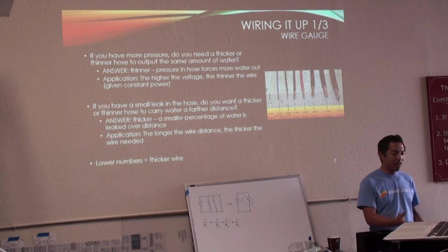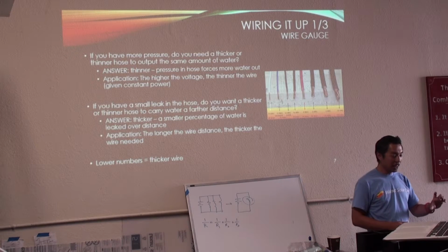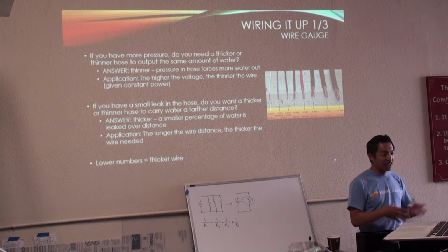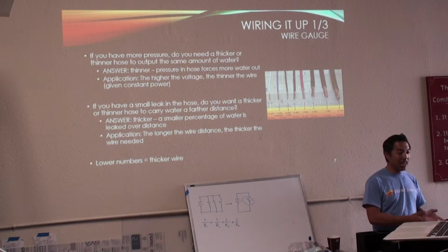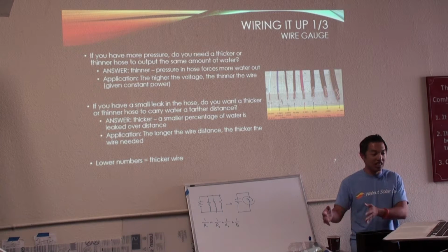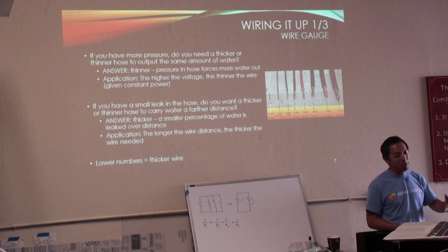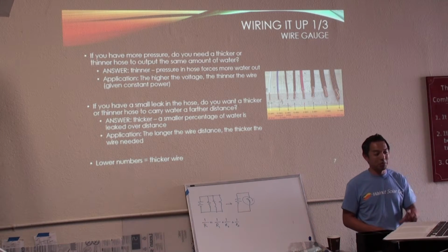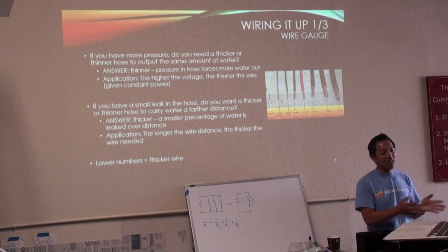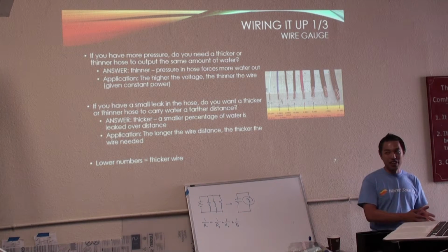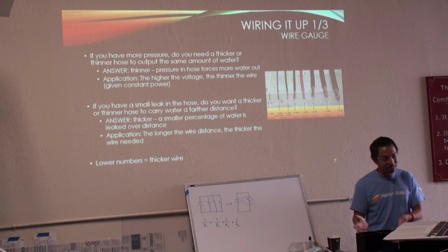So if you have a battery that is 10 amp hours, it means that you can discharge 10 amps over an hour, right? So given that current increases and the voltage stays the same when you wire things in parallel, if you have two batteries, you can then have 20 amps over that hour, 3 batteries, 30 amps over that hour, and so that's how you can add the capacity, because 20 amps over an hour, 30 amps over an hour just means 20 amp hours and 30 amp hours.